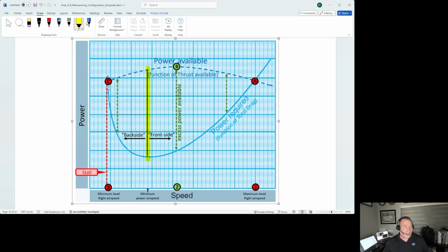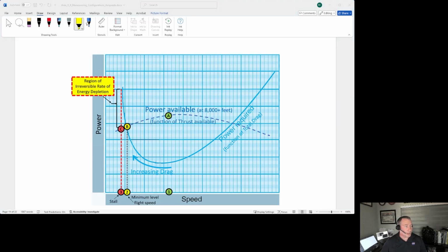It's opposite day from what happens when we're on the right side of the minimum power airspeed. So, the region of reverse command. Now this is a truly interesting diagram. It looks really familiar once again, but it calls attention to a new concept. They haven't bothered plotting out the minimum power required speed, but we can see it down here where my cursor is. Imagine that you're up here at the speed at point A.